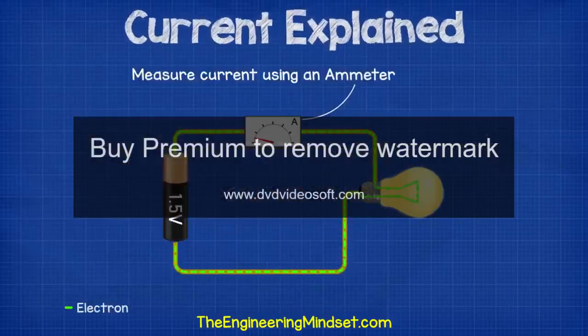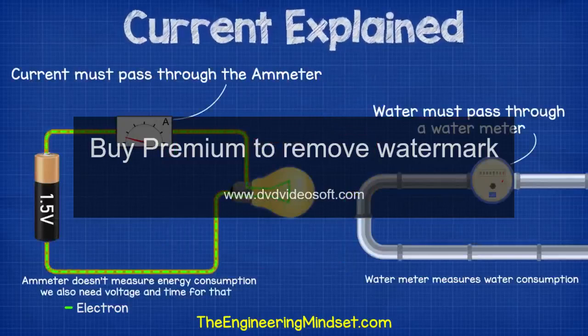So to measure the current in a circuit, we need to connect an ammeter in series so that the current flows through it. Think of it like a water meter. The water needs to flow through the water meter for us to know how much water is flowing in the pipe. Likewise, we need the electrons to flow through our ammeter so that we know how much electricity is flowing in our circuit.